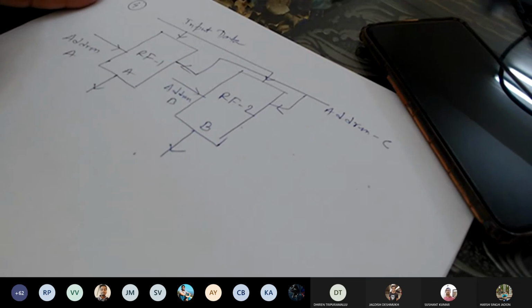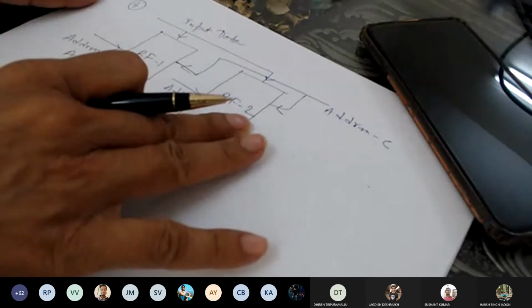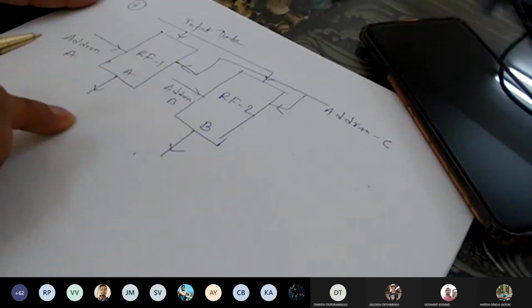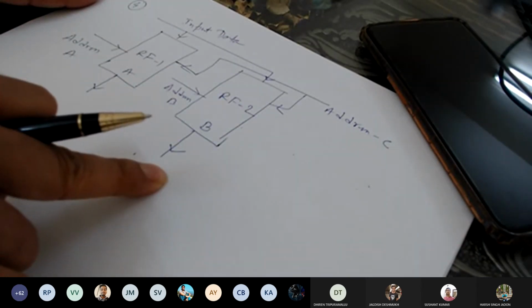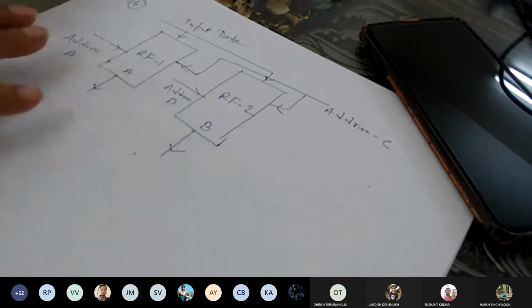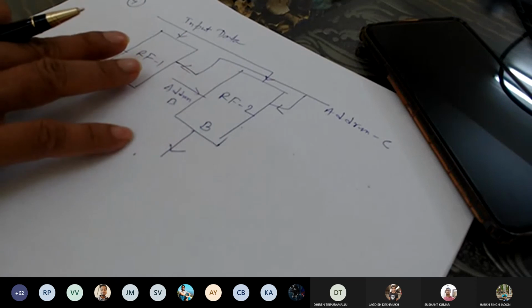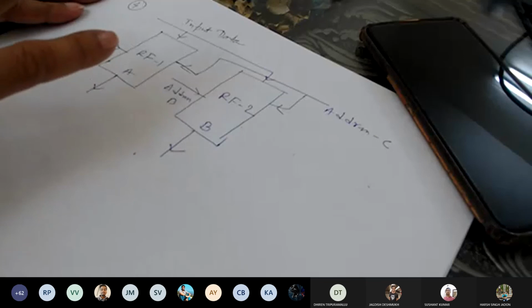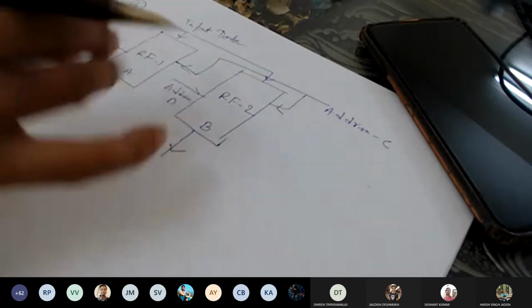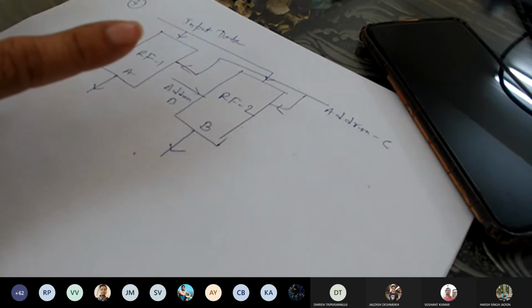So you have two memory blocks here. Both are copied here basically. The register files are here, same. So address A goes, the value directly comes. Address B goes here at the same time, the value directly comes. Basically, we are separating the output ports here. While implementation, you will find why these two approaches; I'm leaving it to you to realize which one is better for you. My objective is I need both the values at the same time and with minimal circuit requirement.